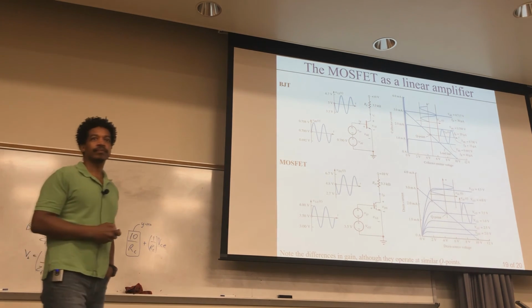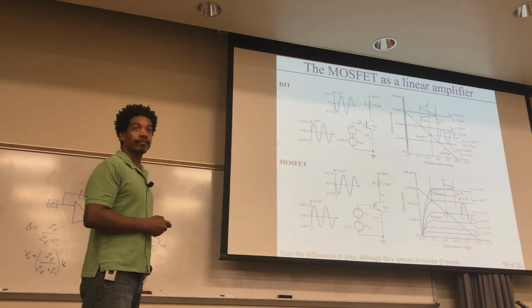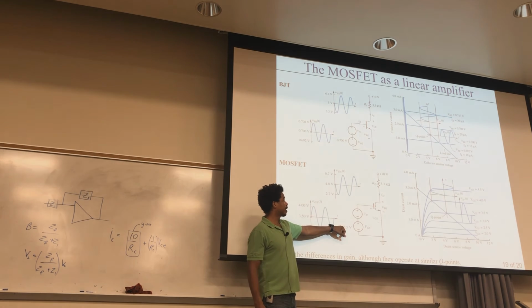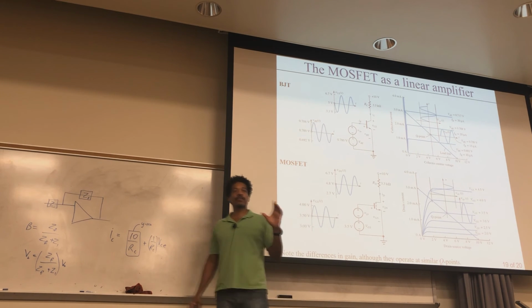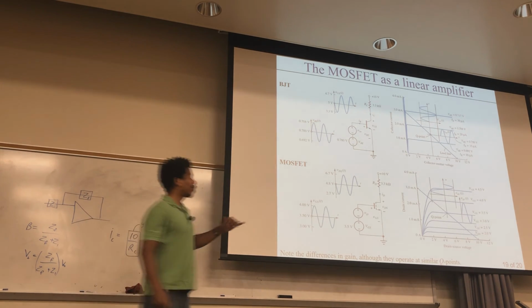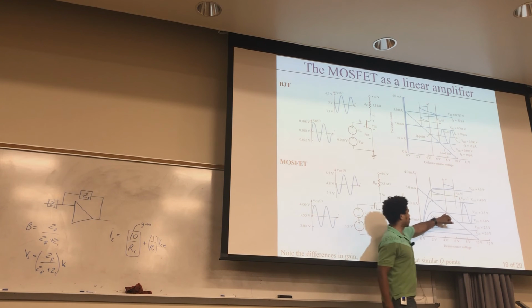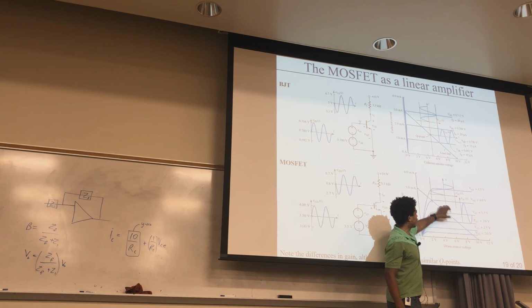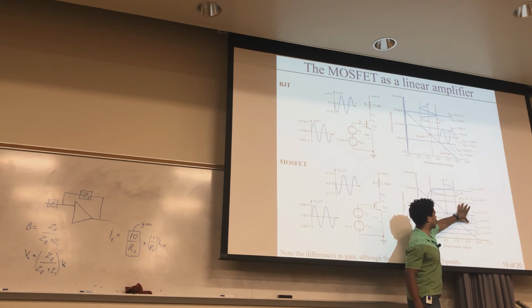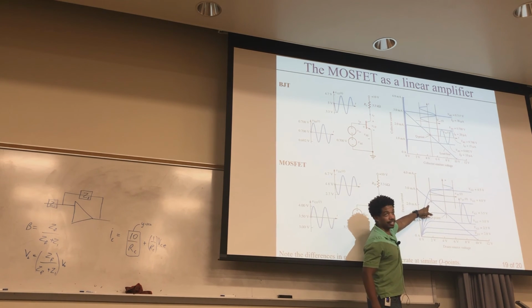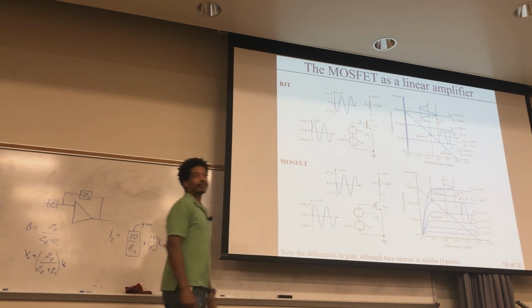Yes. Oh, yeah. So these Q points, from what I gather from the book, are likely different for what you get. The manufacturer would tell you where the Q point is. But once you're around that Q point, which could be slightly different depending on what type of transistor you get, then you're able to do your oscillation. But then it puts a limit. You can see here, this one right here is almost at the limit before it starts changing. So you want to be careful about that.